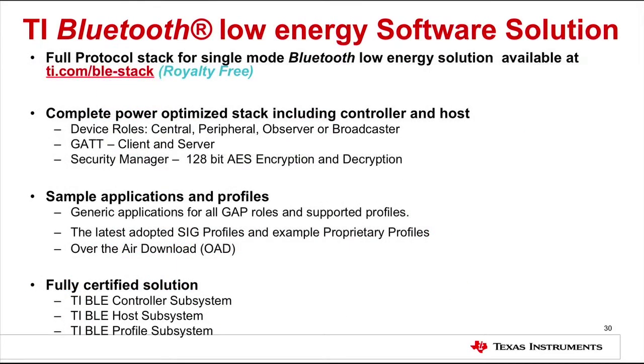All right, let's talk about the software solution a little bit. In the Bluetooth Low Energy solution, TI is providing a royalty-free stack that's available online. There are a couple of different pieces here. It's really an optimized stack for the solution. All the different roles that I talked about are supported. You have GATT with client and server modes, and then the security manager as well, which has some encryption in there. So it gives you some security, which is standard within Bluetooth.